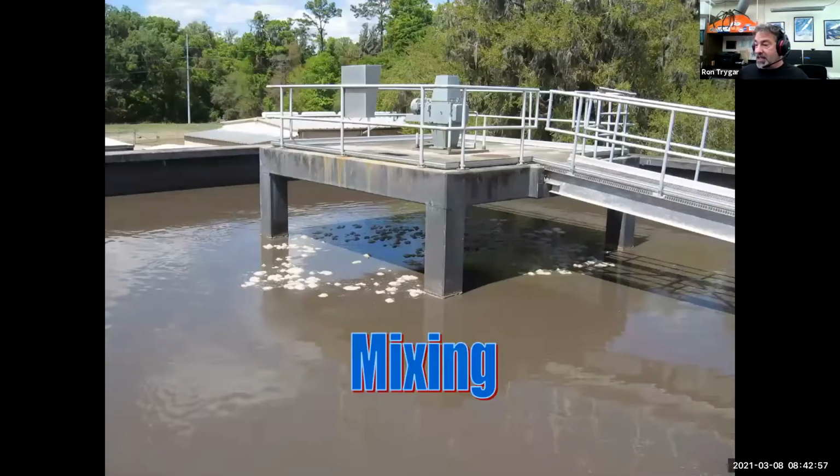So when we mix the tank, we incorporate into this anoxic basin 3 waste streams. We're going to incorporate the influent sewage. That's going to represent our carbon source, the influent sewage, or if you have a primary clarifier, it would be the primary effluent into this basin. So the influent sewage contains the BOD and the CBOD. That's the carbon that we need coming in. It's essentially the CBOD we're looking for.